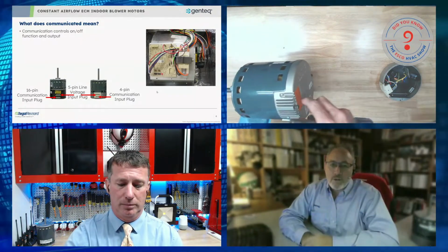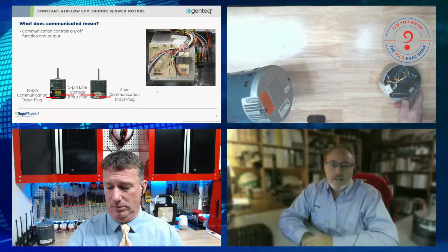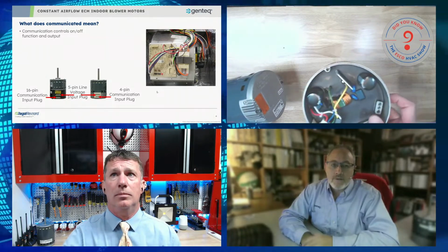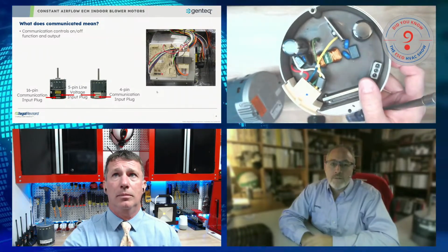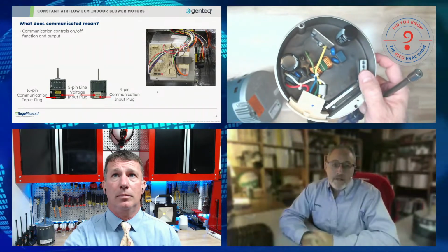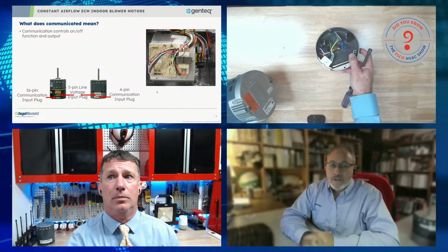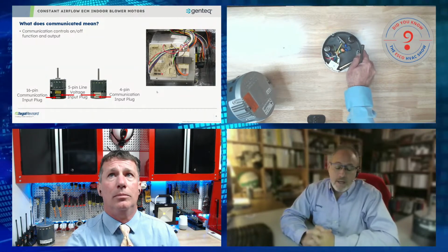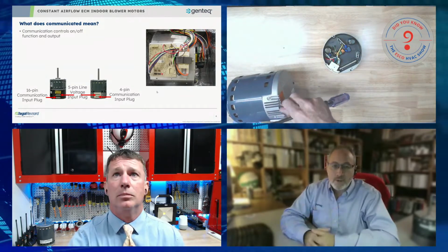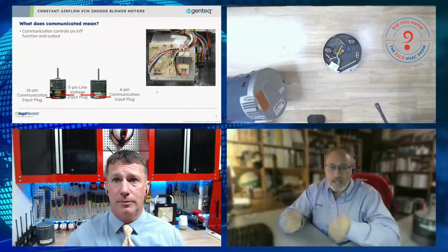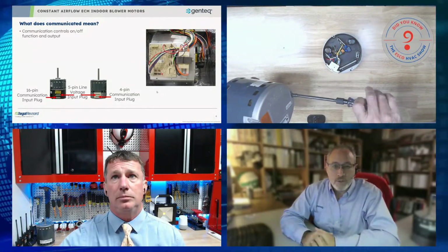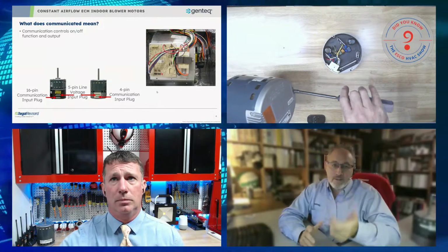If you look at that control that's next to you there, inside, you're going to see some little capacitors. Look at those cute little guys. Aren't they adorable? Those capacitors are about 1,000 microfarads apiece. So they carry a punch. The reason I bring this up is I get asked all the time, why is the motor continuously powered? Why not switch the line voltage on and off instead of switching the communication? And it's because of those capacitors.